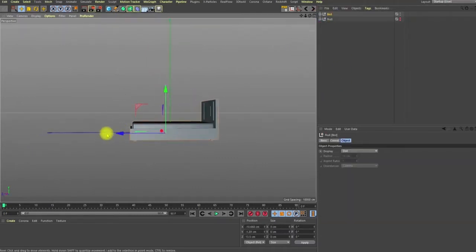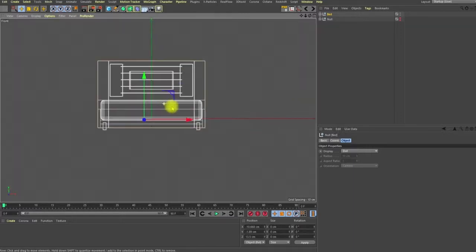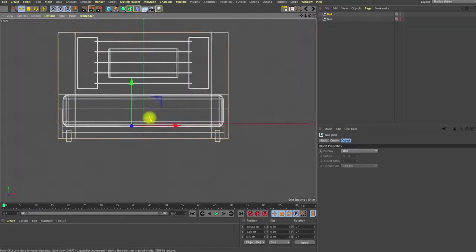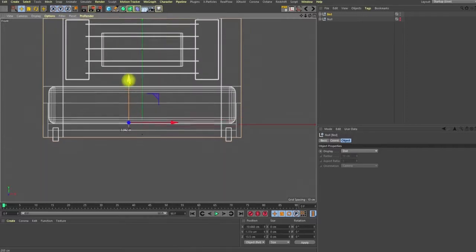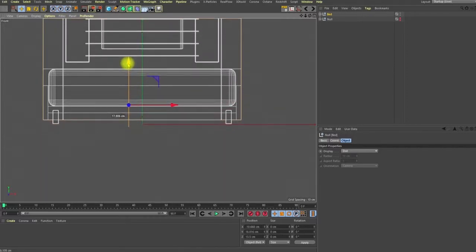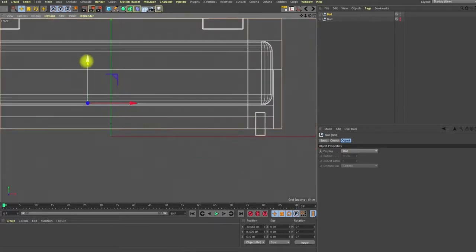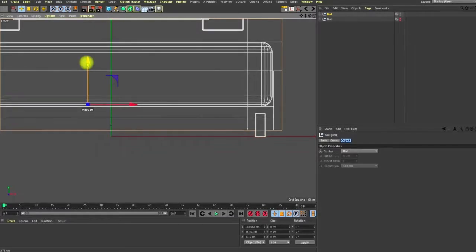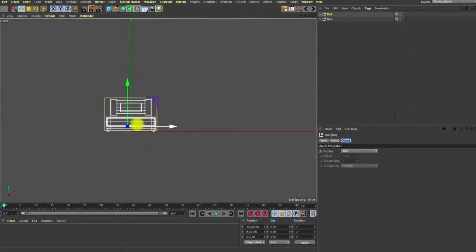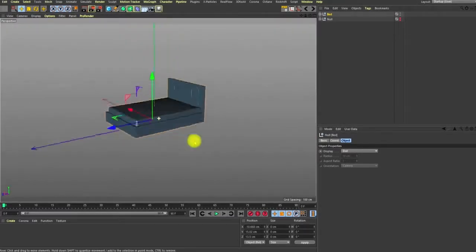If you notice, this is the ground floor. So if I go to the front view, for instance, you notice this is the ground level. We need to move this such that the leg is on the ground. And by the time we take this to CLO, it doesn't interact with the floor and the simulation will have issues. So once I have this on the floor, set, and every other thing is perfect,